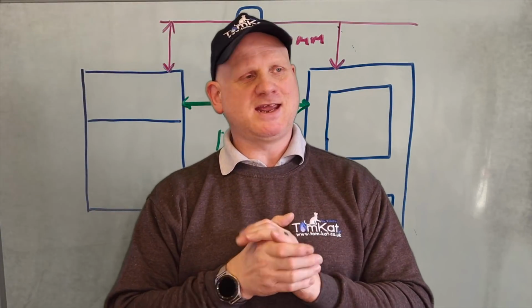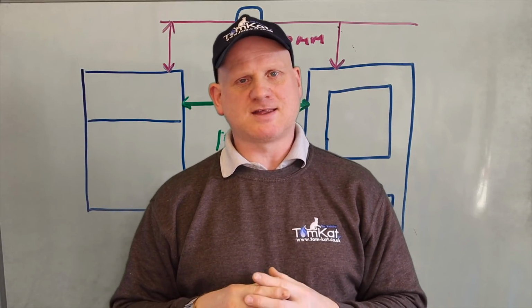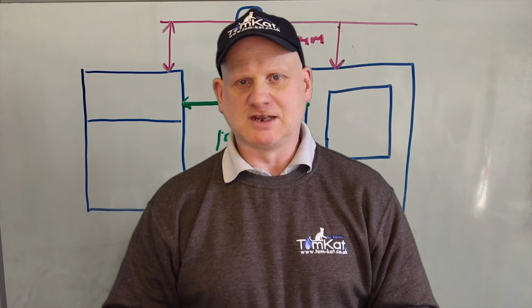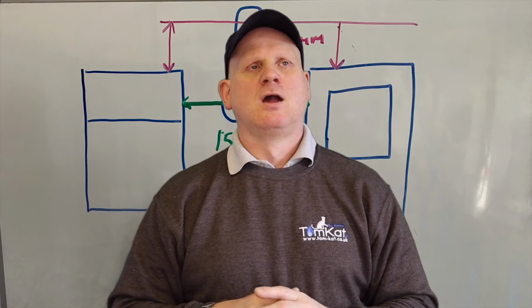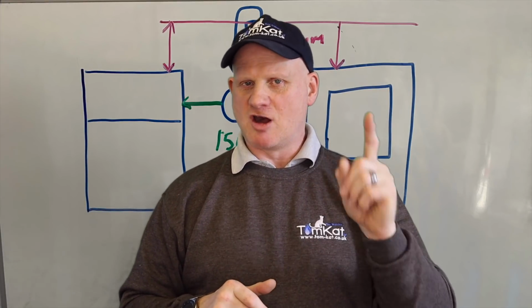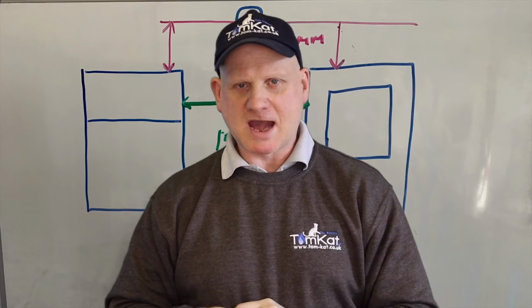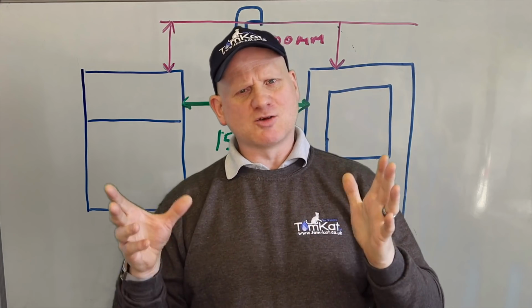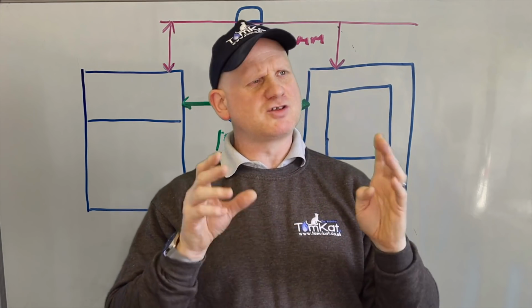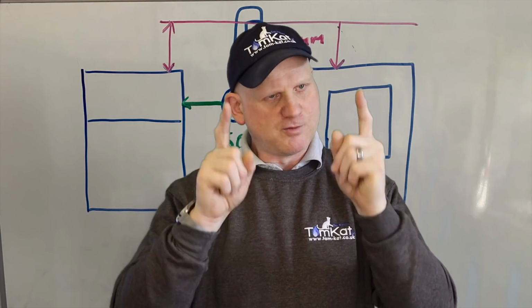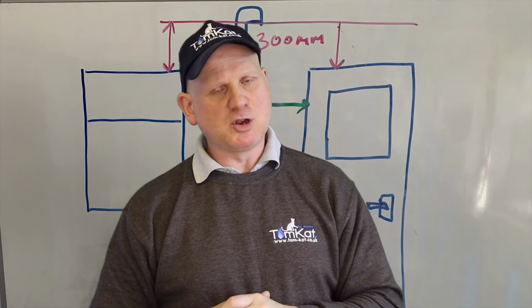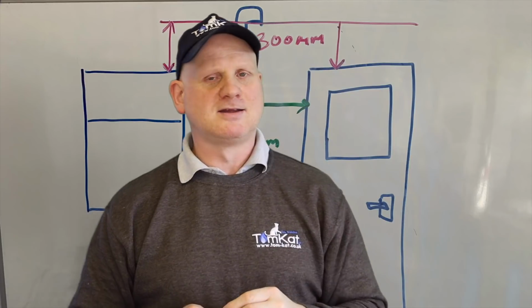Now, at the beginning of this section, I said you cannot use a Plume Management Kit to get you out of an illegal installation, unless the manufacturer of that boiler tells you that you can. So let's take Worcester again. Now there are some manufacturers who are the same as Worcester and some who are different. So again, read those manufacturer's instructions. And what they say about their plume kit is what's behind me here.